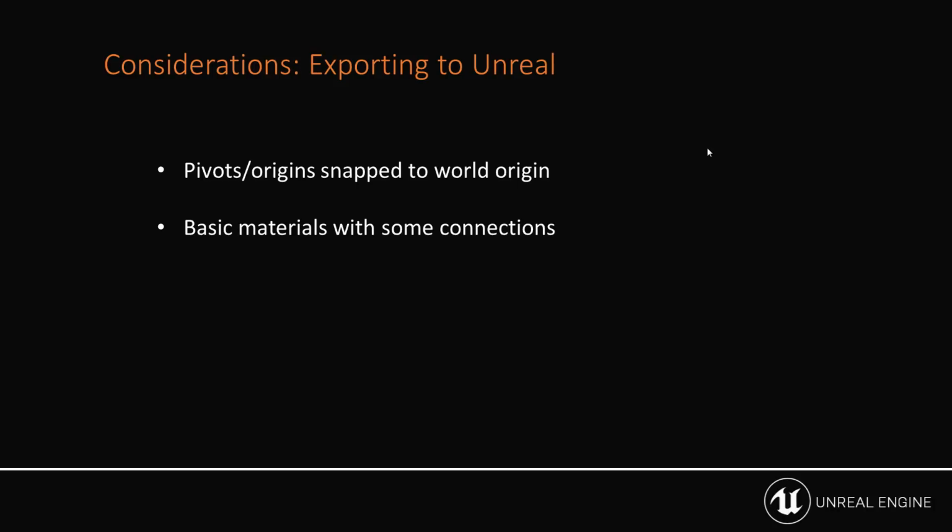So some positional data for certain lights will come over through FBX, but we may lose a lot of the lighting detail. In fact, the entire light might be gone as well. So simple lights may translate, but if there is something more complex going on, we are just going to be left with essentially the positional data of where those lights live. And basic cameras. Anything related to specific camera lensing or anything more complex on a camera is going to be lost in there as well.